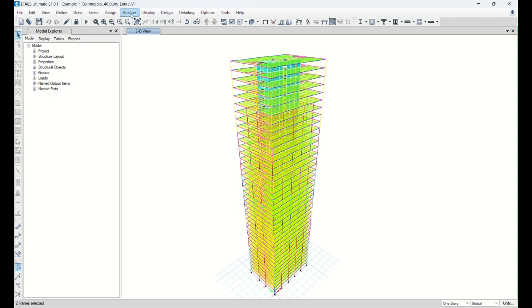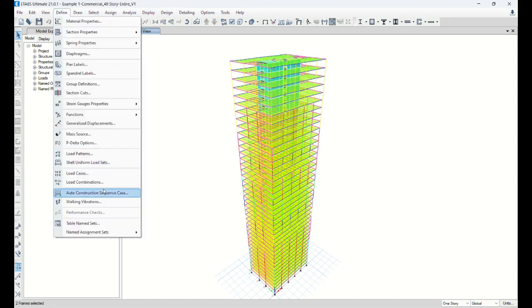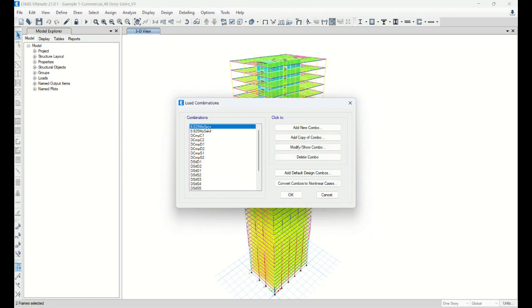One thing I want you to make sure of is that the current ETABS version adopts the latest ASCE 7-16. They are using the ultimate wind loads. So when you define the wind speed, which is 117 miles per hour, you end up with the ultimate wind load. That is the wind load you're going to use for the overall strength design.